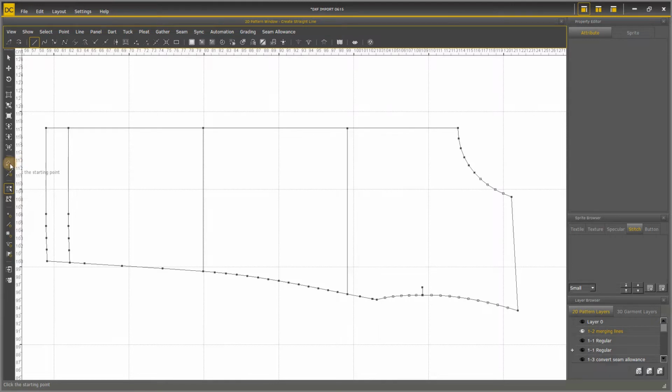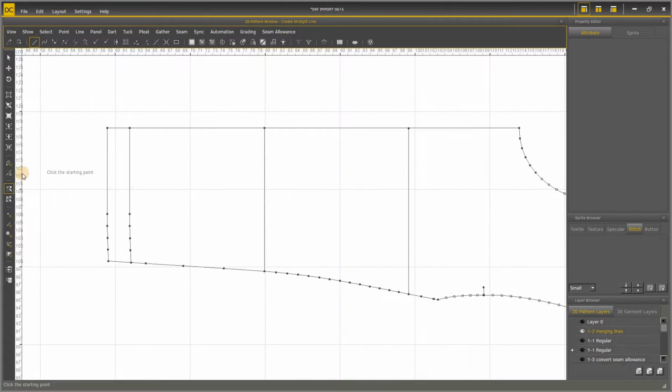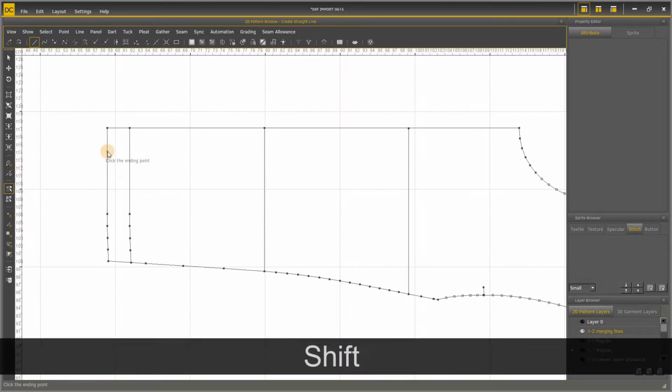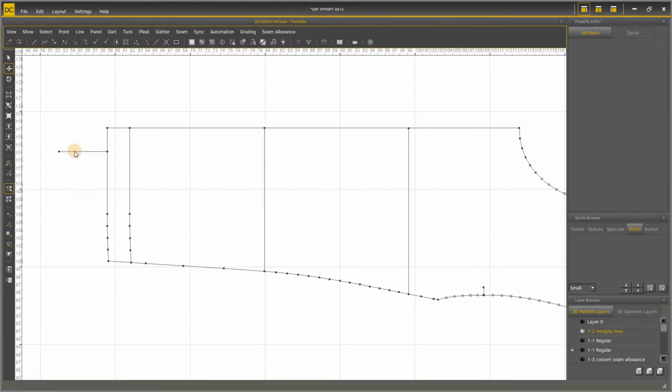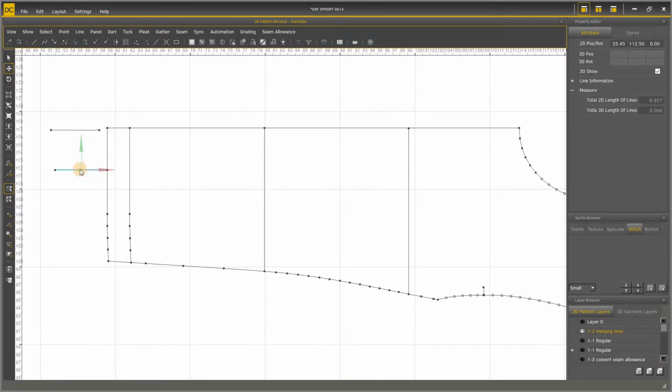The difference between snap and split is that if only snap is turned on, and we snap to a position on the line to create a straight line, when we move the created line away, the original line is still the same. But if snap and split are turned on simultaneously, the line you snap to will also be split into two lines from the snapped point.